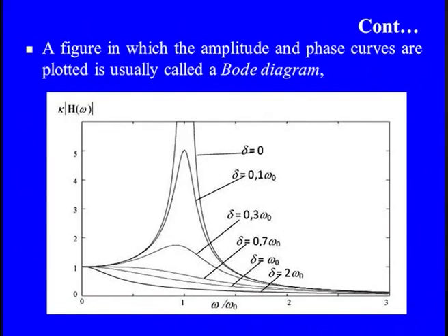Or else, if we go towards the higher order, we know that over damping provides some kind of effective damping, but at the same time it will delay your steady state outcome. We want to quickly damp this out, which, as we already discussed, is featured in the critical damping part. So this is one, and second, we consider the phase differences.